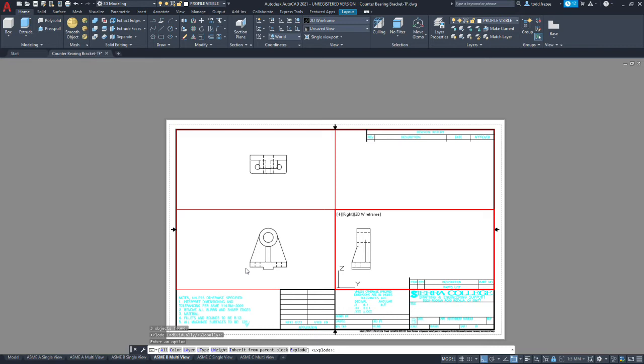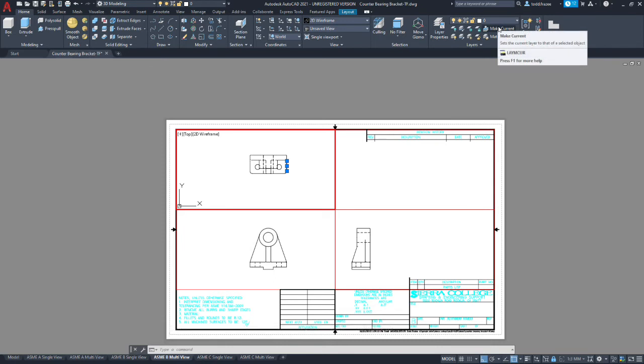We're going to do it by layer, color, line weight. So we're going to put in line weight, LW, and hit enter. And then it asks you the new line weight, what designates it. And we're going to do that by layer, which should be the default. Okay. So now, if we go and select our views, they're individual entities and they've all been moved to layer 0. So now we go through a process of sorting the information onto the proper layer, and it'll take on the line weight of the layer they're moved to.